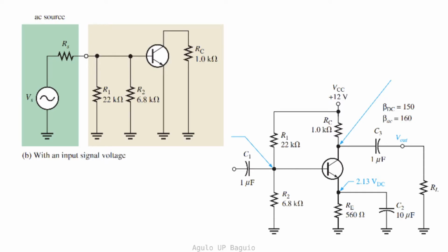The DC voltage source has an internal resistance of 0 ohms as seen by the AC signal, since it holds a constant voltage independent of the load. Thus, no AC voltage develops across it so that it appears as an AC short. This is why a DC source is called an AC ground.